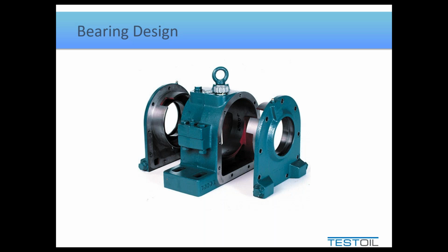But evidence that it was being over-greased had been there for 3 years. So, like I said, I'm not saying it took 3 years for overgreasing to manifest itself. I'm suggesting it took less than 6 weeks for the actual, really significant overgreasing to cause the problem. But evidence that there was some overgreasing had always been there.